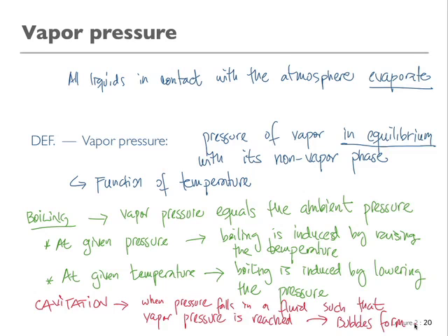Now, as the bubbles move along to other areas of the fluid where there is a larger pressure, they collapse. And when they collapse, their shape changes in such a way that they produce a high-speed jet that can damage materials hard as steel. Let me show you.